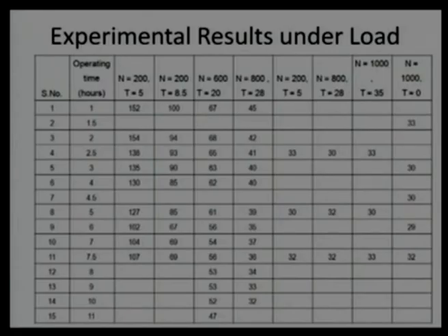If there is a possibility that a light load is introducing vibration, we should not introduce it, and that is a typical example for the rolling element bearing. Whatever the dynamic load capacity of the rolling element bearing, we should never apply a load lesser than 3% of that.